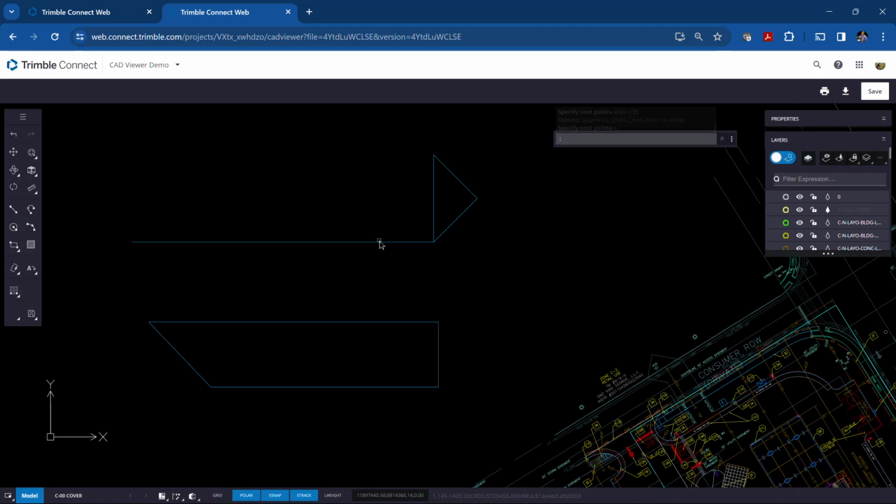So there's ways that you can be precise when you're entering in your line segments by putting in either XY values or putting in angle and distance. So from an XY value standpoint, I showed you a few minutes ago how you would type in the northing and easting, but let's say that I go here and I want to go from this point an XY value.